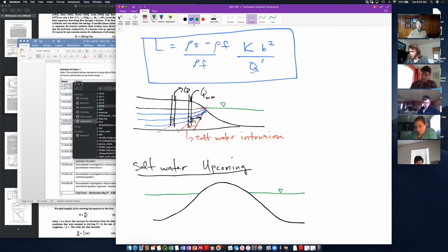All right, and we had this freshwater water table, and then our interface between the two looks something like this. All right. So if I put a pump in, say here in the middle of my island, and I start pumping out groundwater, we're going to talk all about this, but essentially what we do is we induce what we call a cone of depression around the well.